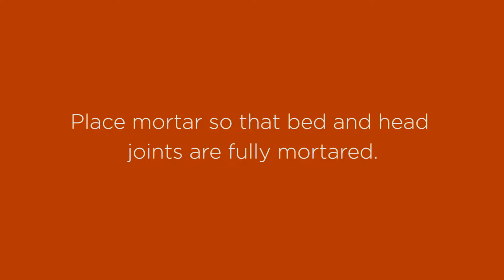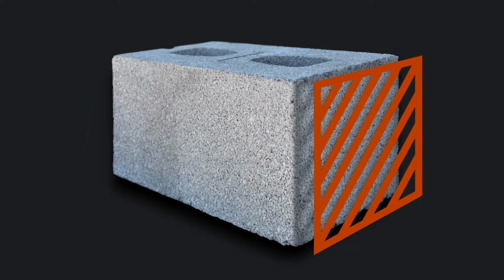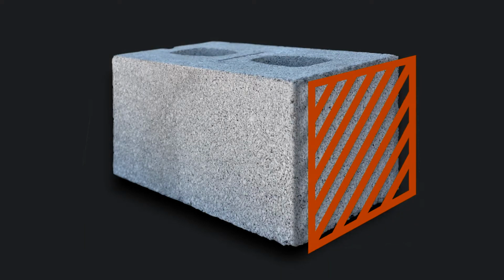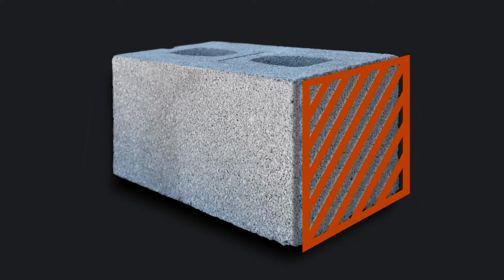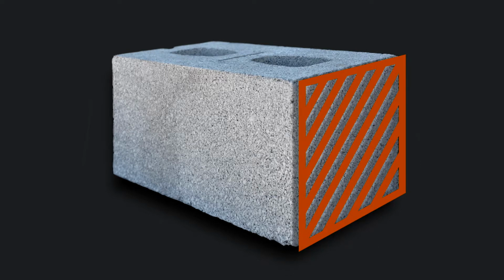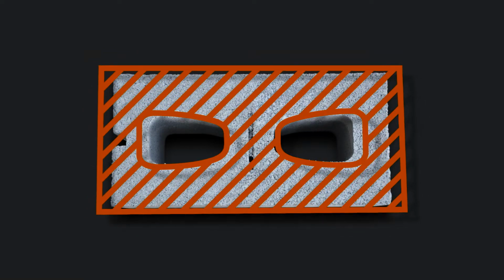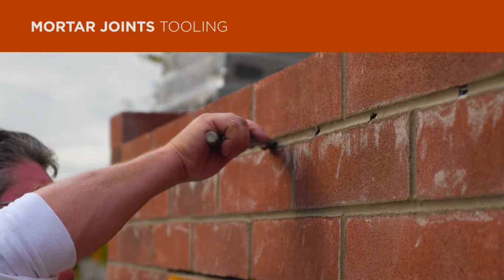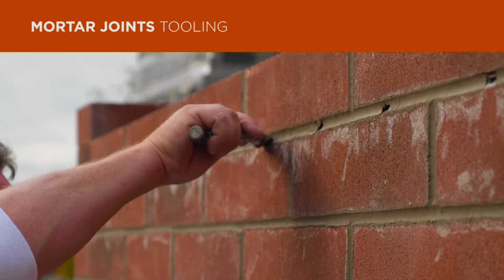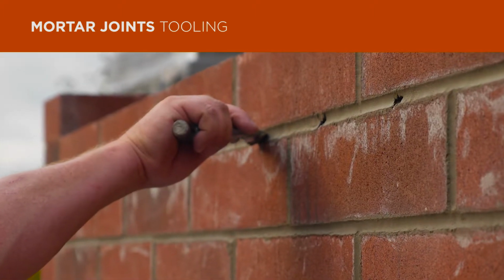With solid units, there are a few different rules. Place mortar so that the bed and head joints are fully mortared. A full head joint on a solid unit covers the depth of the unit to the width of the head joint, typically 3/8 of an inch wide, the full height of the unit. A full bed joint on a solid unit covers the depth of each face shell, plus any solid portion of the web material, to the height of the bed joint, typically 3/8 of an inch, the full length of the unit. The code requires that all holes that are not specified to be in the mortar joint be filled, below grade as well as exposed masonry.